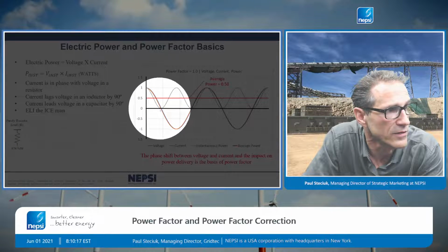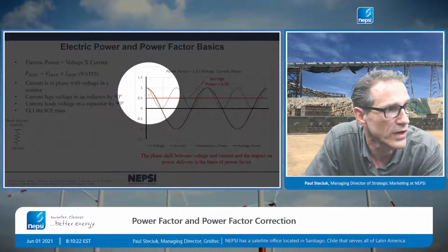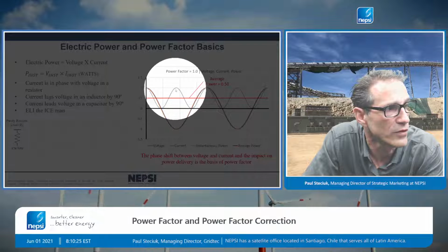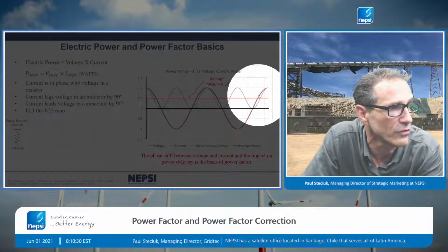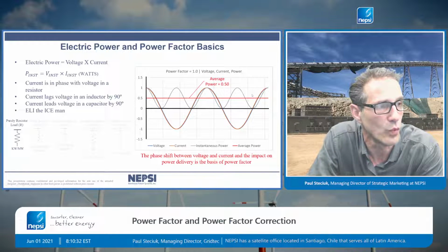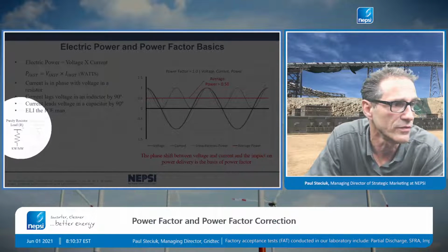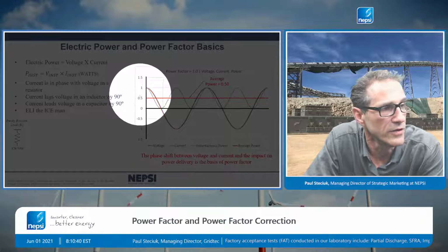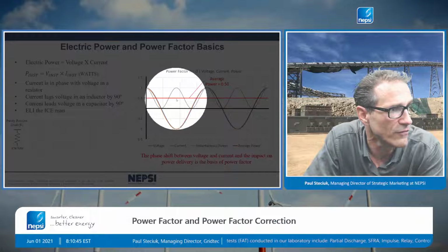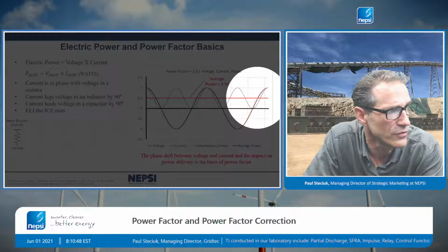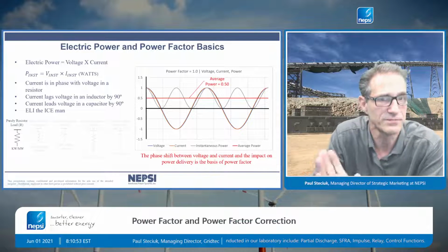And then I could take 0 times 0 and have 0 here, and I could take 1 times 1 and have 1 here. So obviously what you get is a gray waveform here, and this is the power flow, the instantaneous power flow into a load that has a power factor of 1. Okay, it's a resistive load. It's what I showed down here, resistive load, a value of 1. And if you do the calculation, you get a value of 0.5, the average power flow into the load. So volts times amps along the whole waveform. The average power is into the load.